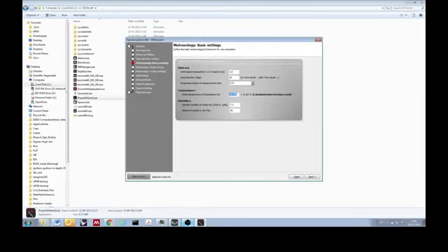Here you can set the temperature of your model. This is the initial temperature, but the temperature will be recalculated from this according to the solar radiation and your site. You have to change this according to which kind of simulation you want to do. Now we are making a summer simulation, which means that we can assume a slightly higher temperature.